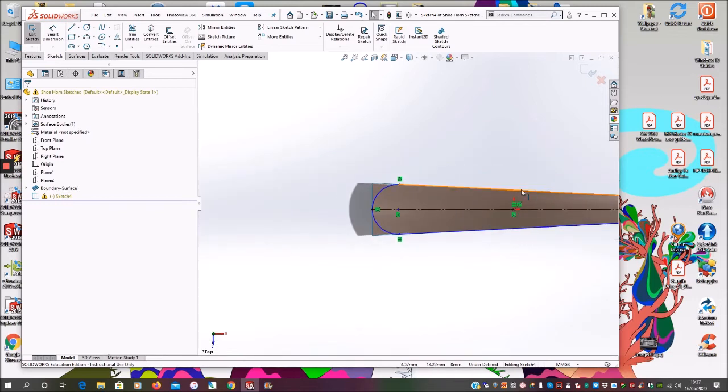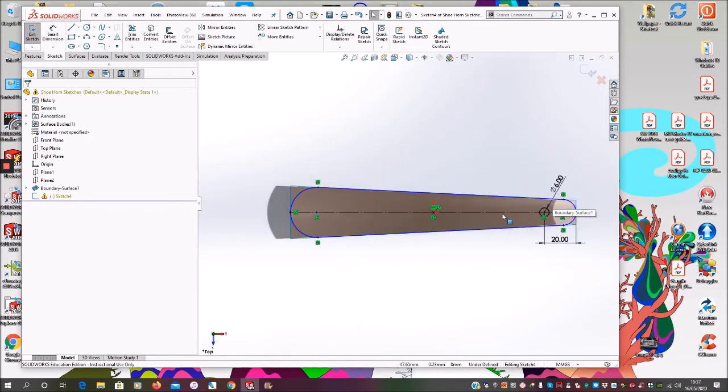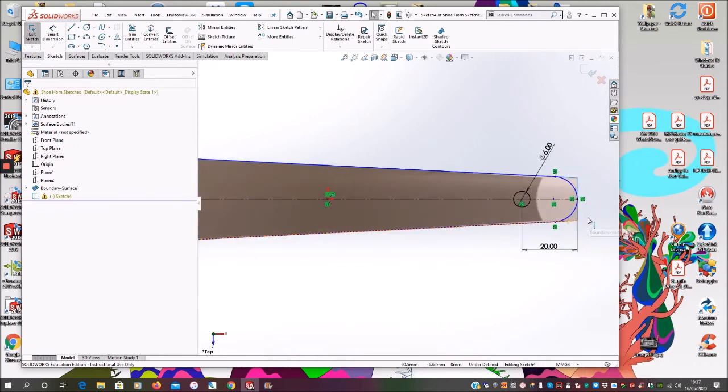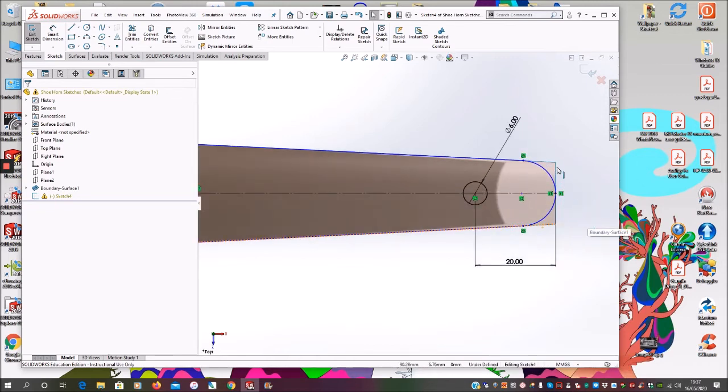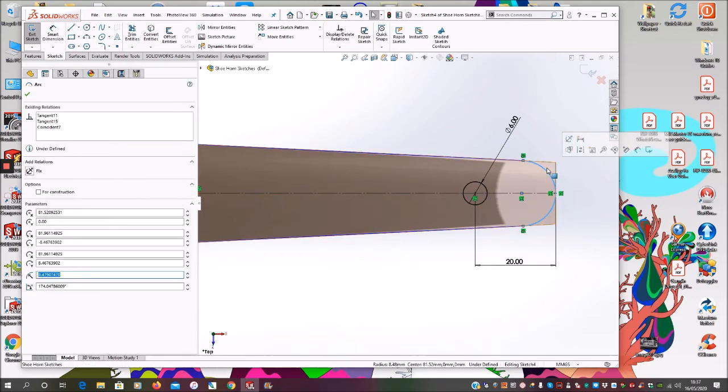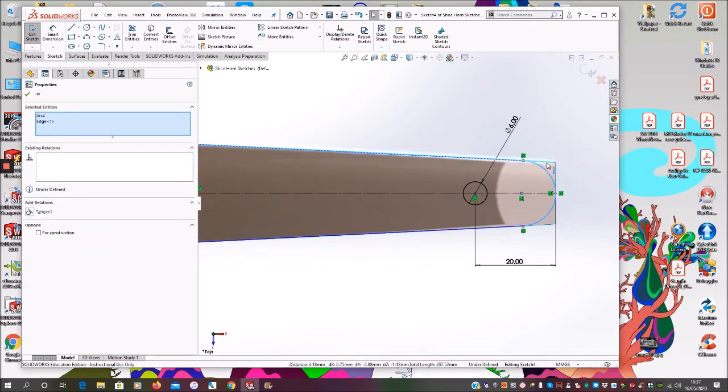See that one, I don't know if you noticed, but that one has automatically disappeared. So those dangling entities were because I'd created this shape already and then deleted it to leave the sketches. It had constraints to this edge which had been deleted. So if we select, Control select, and then we can add a tangent relation at that end.